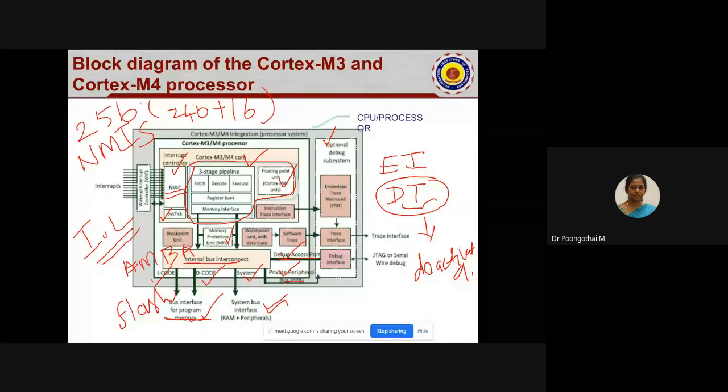So that is the meaning. Non-maskable means we cannot disable the interrupt source. Is that clear? Yes, ma'am. So which is better to employ, ma'am? Actually, for critical code execution, we need to assign a particular interrupt source as non-maskable. Let's take the airbag example. The processor is doing some emergency work, so in that case the particular interrupt cannot be disabled. The DI instruction is deactivated during the program, because the airbag should be activated within moments. Suppose that particular interrupt is disabled at that time, then the entire system will collapse. So those interrupts are called non-maskable interrupts.